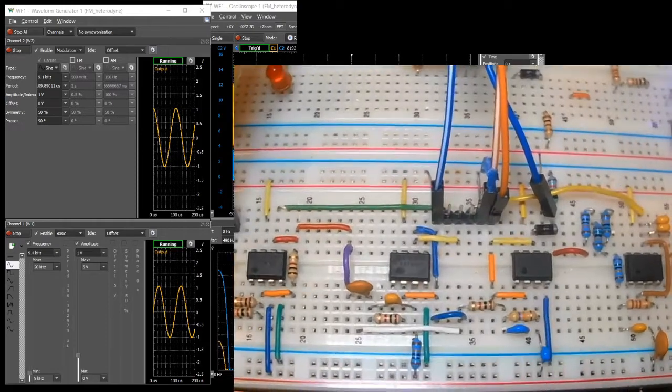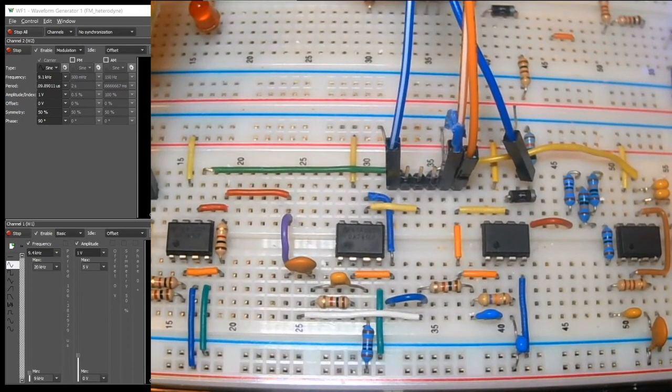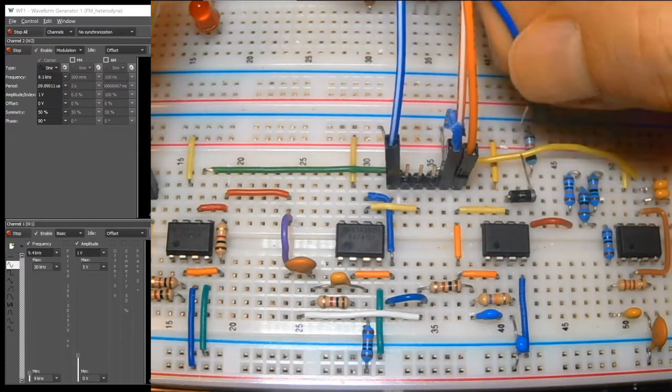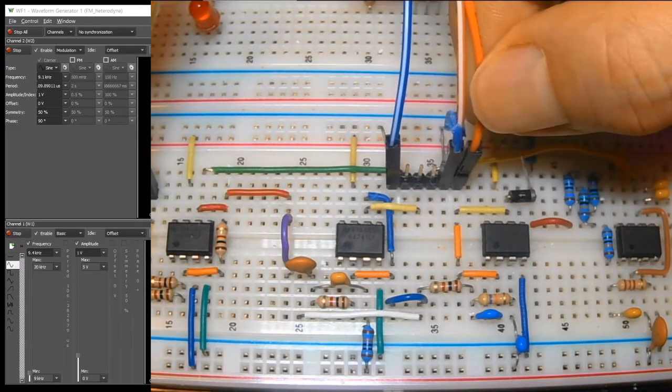The selection of the desired heterodyne component, which is the absolute f2-f1 component, can be done in successive steps. The first step is to use a low-pass filter to block out all the high-frequency components. This is done by coupling the diode output into a low-pass filter circuit.